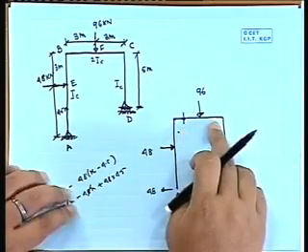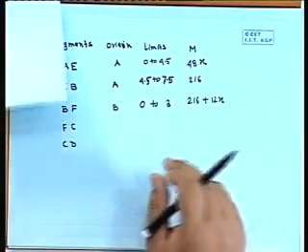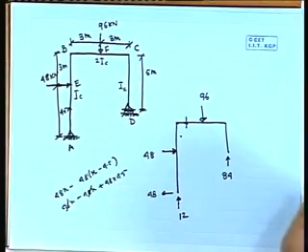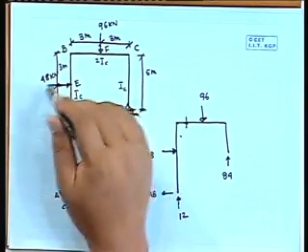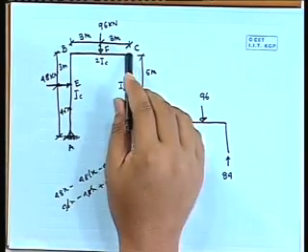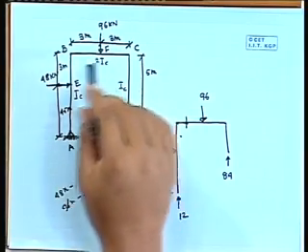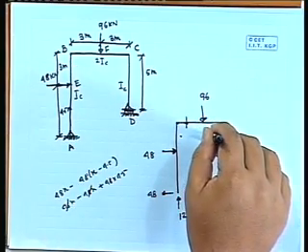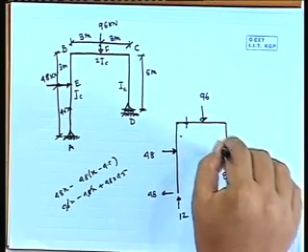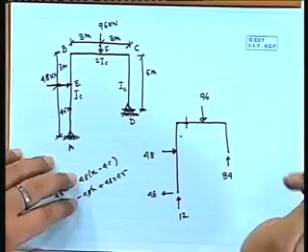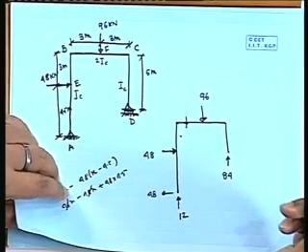Now if I go to the other part, FC, this FC is this part. Now FC, what will be the origin? One option is we can take F, means whatever expression we are getting, plus 96 minus 96 into something we can make. Other option is we can take from this side. I think that will be much easier, because this side is only 48 is the force. If we take a section here, and if the distance is x, it will be just 84 into x. So it is much easier to take from that side. But there is no harm, you can take from this side also.